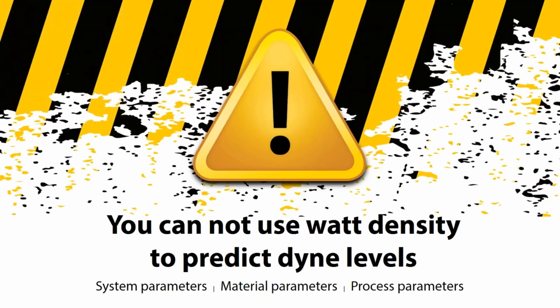So carrying that thought forward, you cannot use a watt density to predict your dyne number. For example, in an earlier slide we talked about typical watt densities for corona treaters being 2 to 3 watts per square foot per minute. Many times I get the question from folks: if I apply a 2 watt density to a polyester film running a certain speed at a certain width, will that guarantee that I get 56 dynes? And the answer is, I can't answer that question.